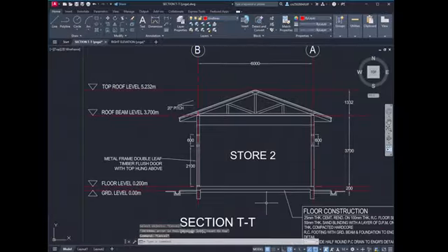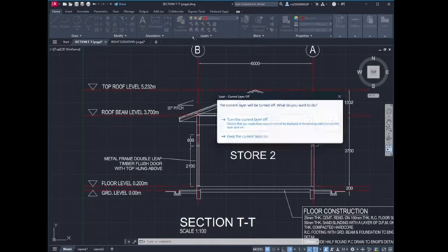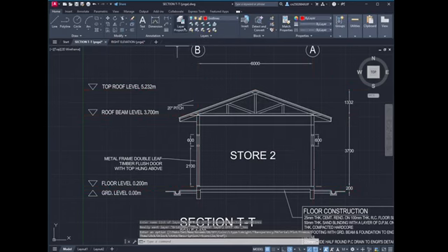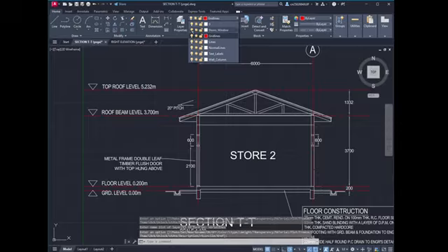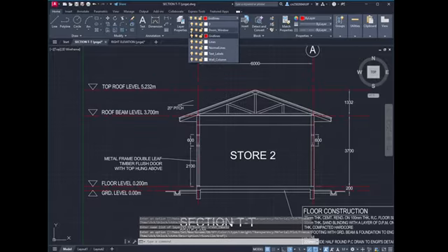To ensure everything looks neat and tidy, I of course used different lines and layers for every single drawing. For example, the grid line has its own separate layer. I can turn it off, and the drawing has its own separate layers, to ensure that I can view everything normally. Text labels have their own separate layer, and doors and windows have their own separate layers.